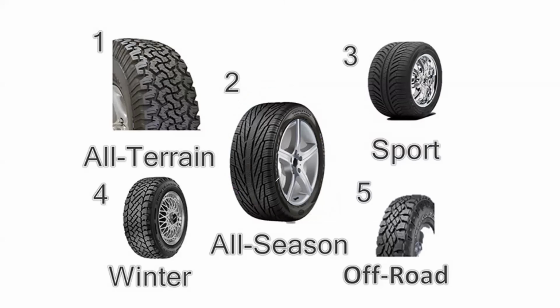But if we remove all these threads, that means there are no threads. If you look at a race car, they don't have threads, unless they are racing in rain. They have a smooth surface. The reason is, if you have threads, that reduces the contact patch when you are going on the tarmac or hard ground.